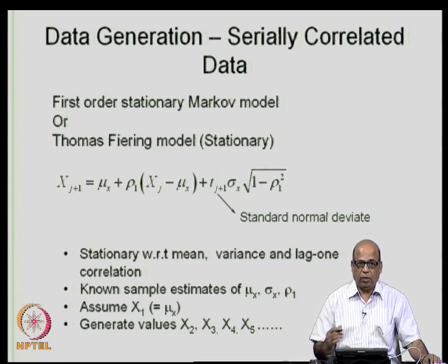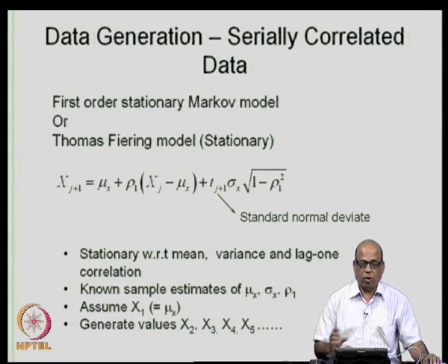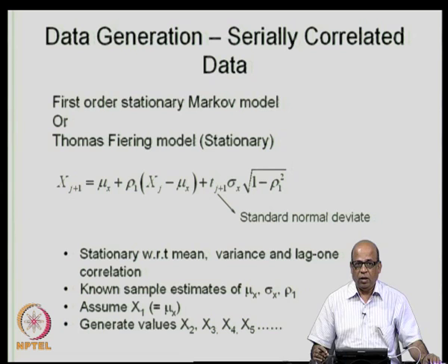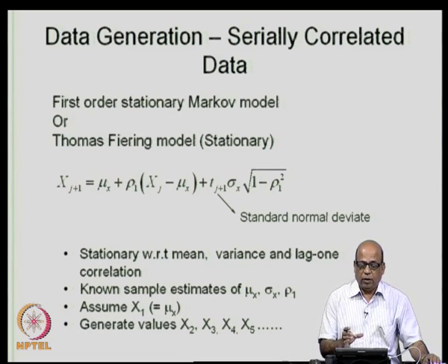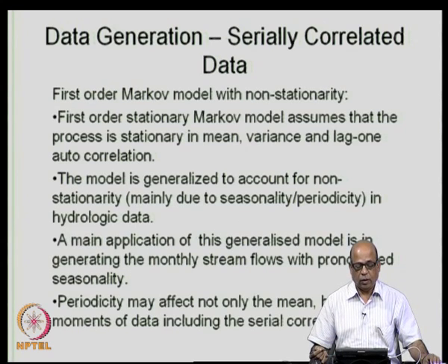The seasons can be either months, in which case we will have 12 periods. They can be monsoon and non-monsoon season, in which we will have 2 seasons, or monsoon, summer and winter, 3 seasons. We may consider 10-day durations, in which case we may have 36 or 37 time periods according to how we discretize. Like this, we will now consider the intra-year periods over which we are interested in generating the flows.